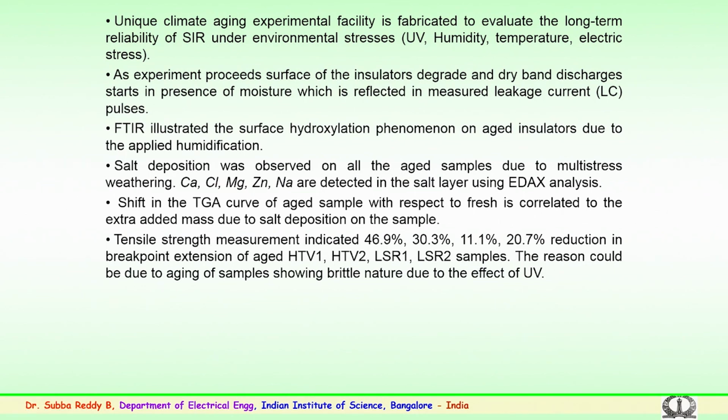So, multi-stress experimentation gives an idea for the long duration performance of the polymer insulators because of effect of UV, effect of humidity, because of effect of temperature, because of effect of electric stress, rain and many factors. So, this experimentation, as insulators are organic in nature, is very important to be conducted.